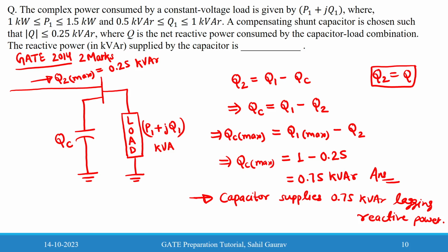In terms of load, what is the inherent characteristic of load? It consumes, that is a consumption property. In capacitor current leads the voltage, that means capacitor consumes the leading reactive power, and in inductor current lags behind the voltage, that means inductor consumes the lagging reactive power.